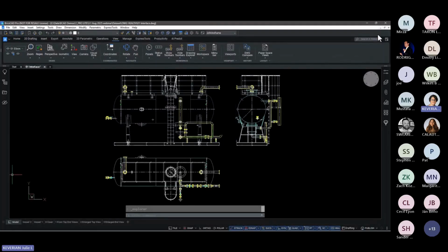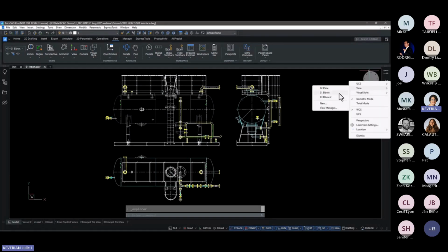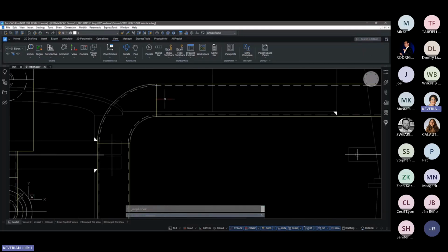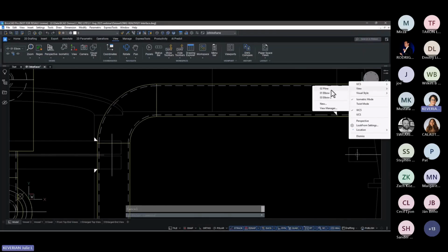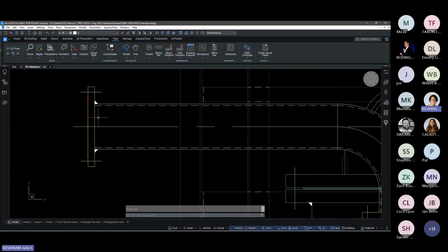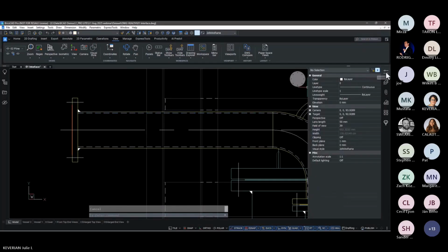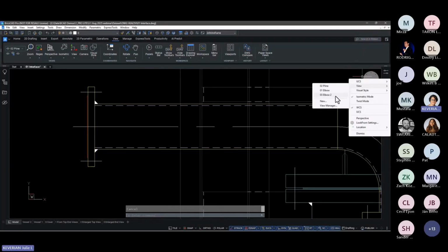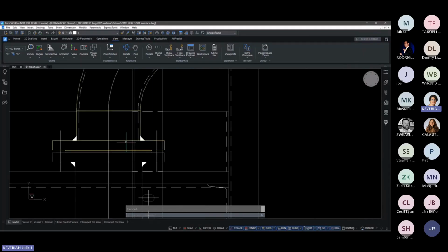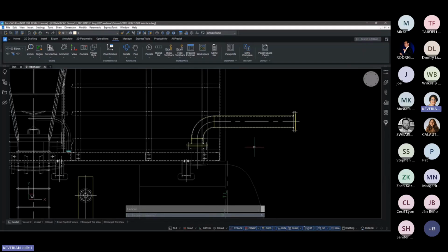So let's take a closer look at some of the graphics in this drawing. We're going to see in one of the pipes and one of the elbows, there are 2 overlapping lines. Only one is needed. Also, we have a very simple polyline, but although it's a very simple polyline, it has 6 vertices. Does it really need all 6? And we'll look at one other spot. We have 2 individual line segments that could very easily be joined into a single line. Now, these are examples of inefficient, or what I call messy, drafting practices.